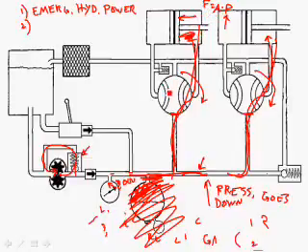So for a second or two or three, the actuators aren't going to be able to push quite as hard as they would have until the engine-driven pump stops the fluid going around in a circle and pumps more fluid into the pressure line to make up for the pressure that's gone. But we're going to have a loss in pressure for a second or two, therefore we'll have a loss of force at our actuators.